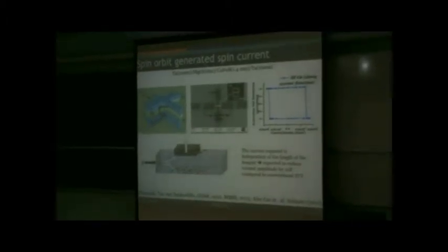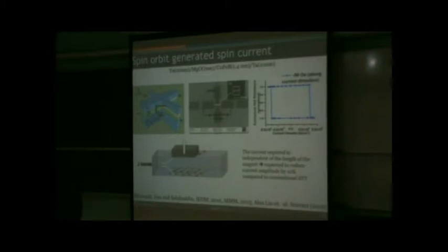And initially a group from Japan, Hideo Ono's group, already showed that in 1 nanometer tantalum, you can actually generate this kind of spin current and switch a magnet, and many other groups have reproduced it, including ours. So this works. Okay? So again, you see that this is a new material system. This tantalum, as a material system, is very old, but we are using this new property of spin-orbit coupling to do something that we could not do before.